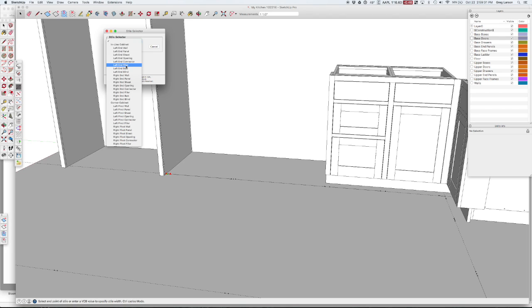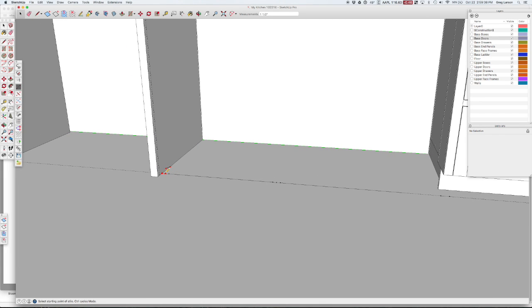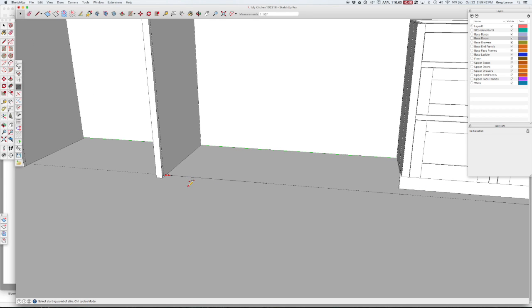It's a generic style and it won't add any additional things, but notice it drew it as 3/4 inches wide. Because there's no style and it's frameless, CabWriter assumes that style is just the width of the cabinet side, which in our case is 3/4 inch. If it was set to something else, that's how wide it would draw the style here on the screen. If I go to this side and do the right end opening,